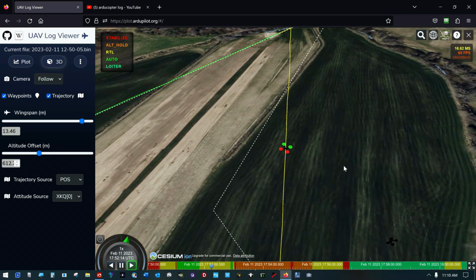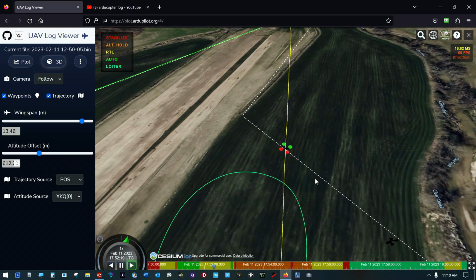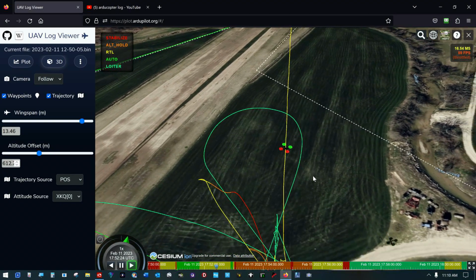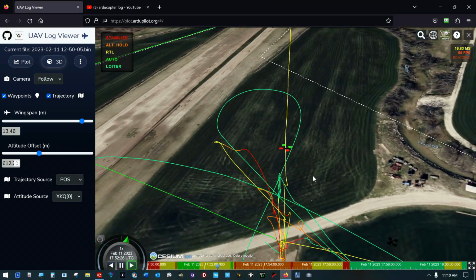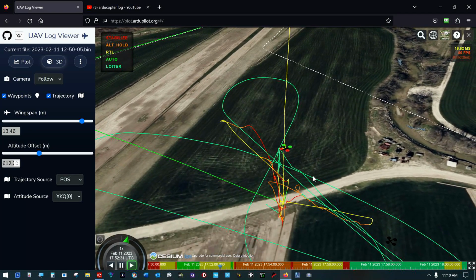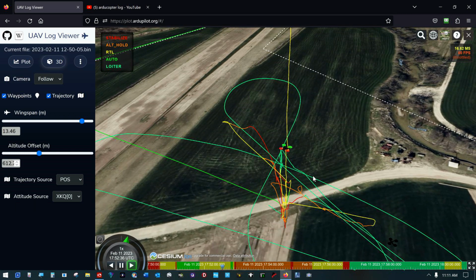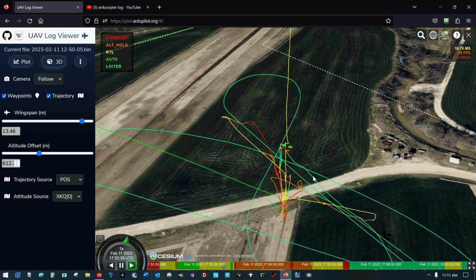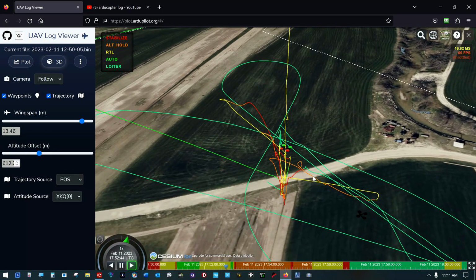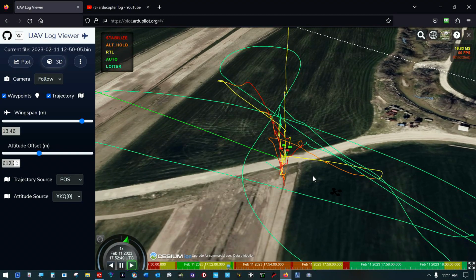And I don't like that. That's why I changed that parameter, so it will turn around and face return to launch. For camera usability, what if you came home like this from 5 miles away? What if you flew out 5 miles, had a radio fail-safe because you dropped your radio on the ground and it broke? It would come home 5 miles backwards like that. So, again, it's coming in for a landing. So, this utility is pretty darn